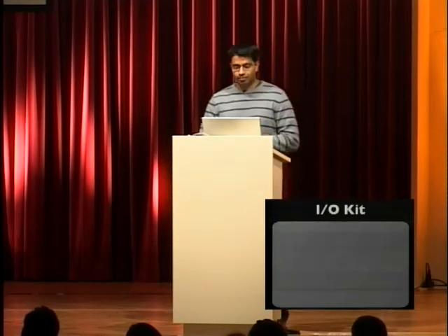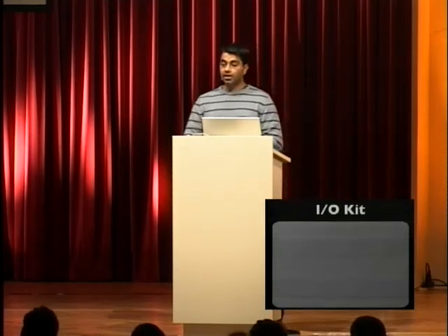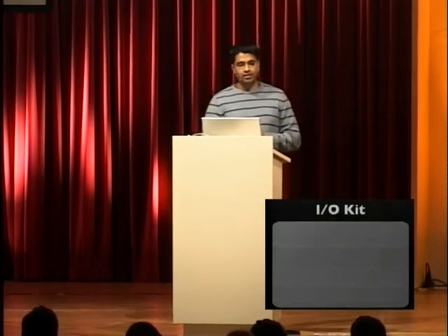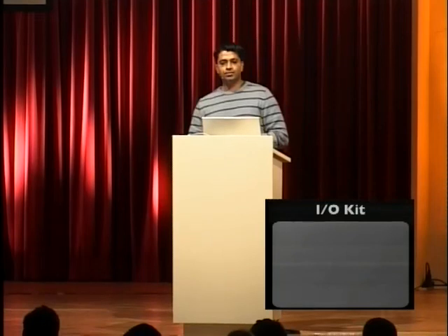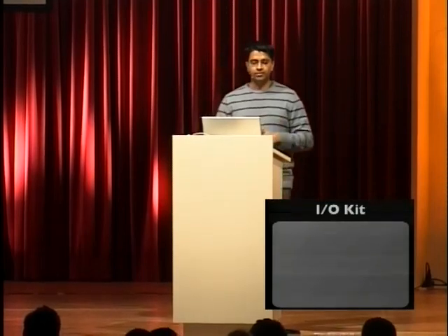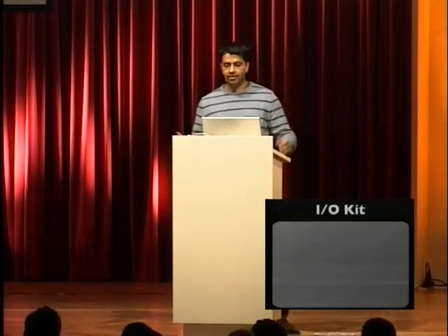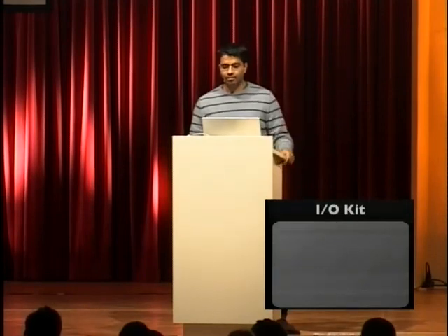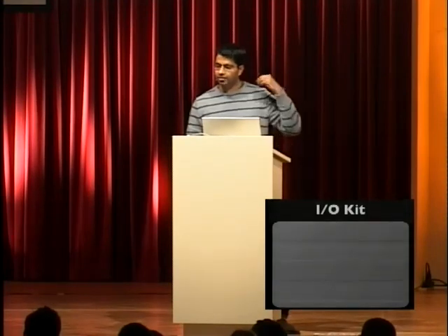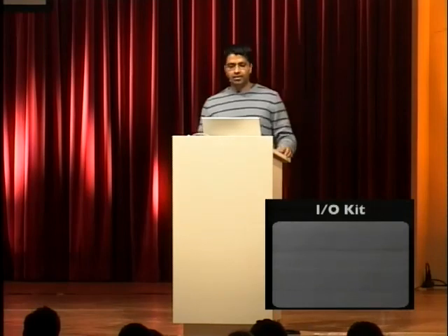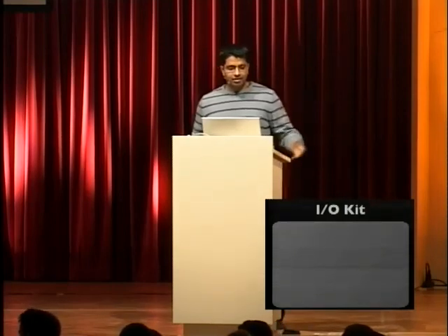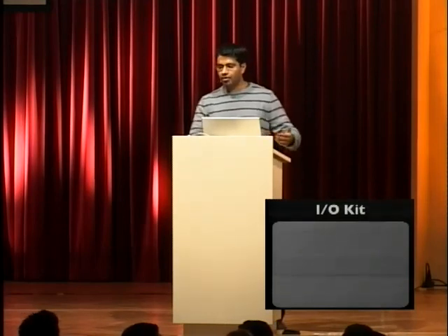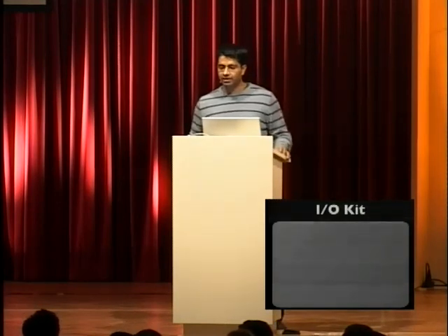I don't want to program more than necessary. So I looked at the Linux driver, and it looks like a very well-written and small piece of code. When you talk to the TPM, you access this thing on the LPC bus, kind of like you access ISA devices, the legacy-style stuff. There's a couple of registers, and you just do port and memory-mapped I/O to these things, and then you drive this whole thing.